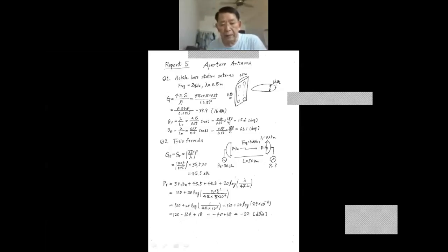Now this is very good received power, considering the rain fading, to increase the reliability of this communication link. This minus 22 dBm is sufficient. When a very strong rain, this can communicate. Okay. Okay, Sensei. So this is almost the answer. Is anyone?